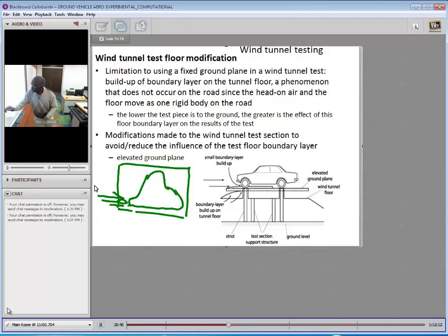Well, as the flow comes here in the test section, because this is a wall by itself, the flow builds up. So a boundary layer builds up, not by the object that you have, but by the sheer presence of the test flow. You have a build-up of air already, and that interferes with the model that you put in. Let's even say you raise the model this high. If you don't raise it high enough, you could still have interference. So the result you'll be getting is based on this flow interfering with this surface because of the presence of this flow.